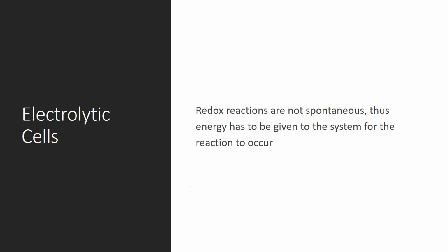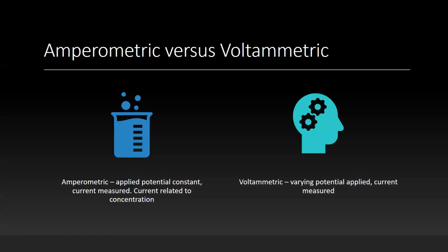For example, continuous glucose meters use these principles to measure glucose in the interstitial fluid. Now, analyzers, like continuous glucose monitors, can be known as biosensors if they utilize enzymes or receptors to establish selectivity to particular analytes. The main two techniques I will discuss are amperometry and voltammetry. Both estimate the concentration of a particular analyte, but they differ in whether the applied potential or voltage is fixed or variable. Amperometry uses a fixed constant voltage, but voltammetry uses a variable voltage.